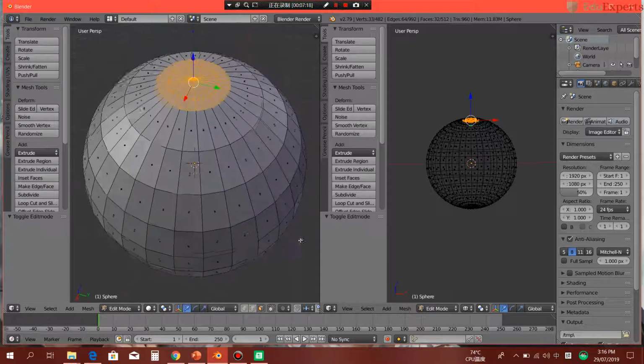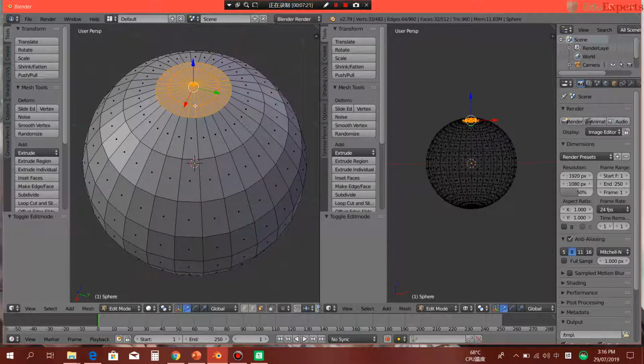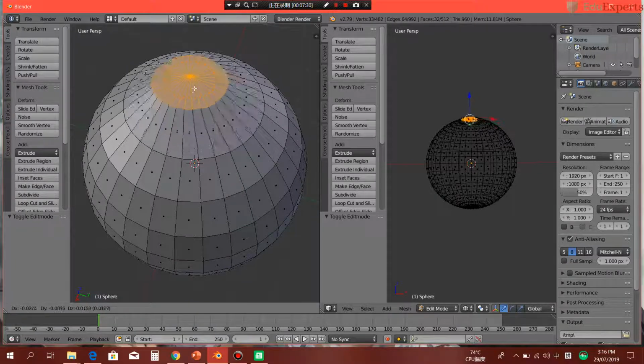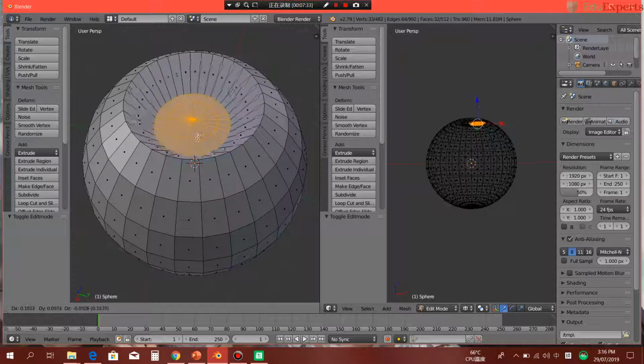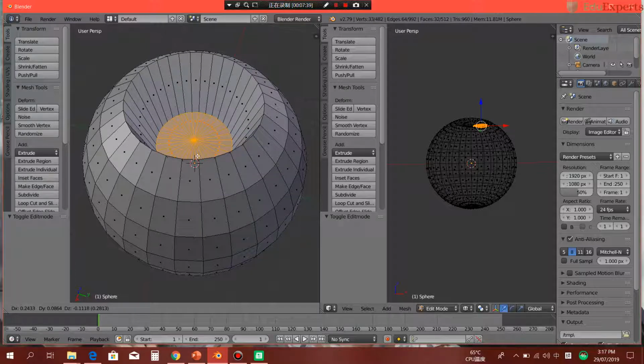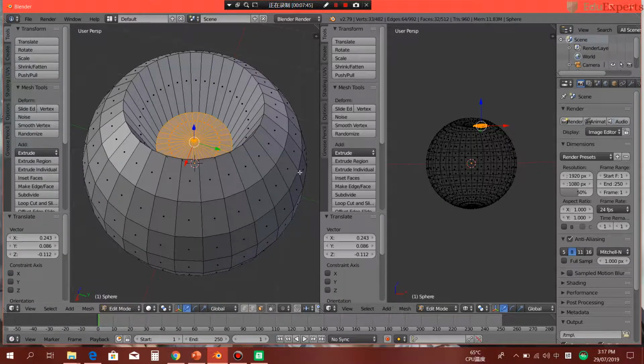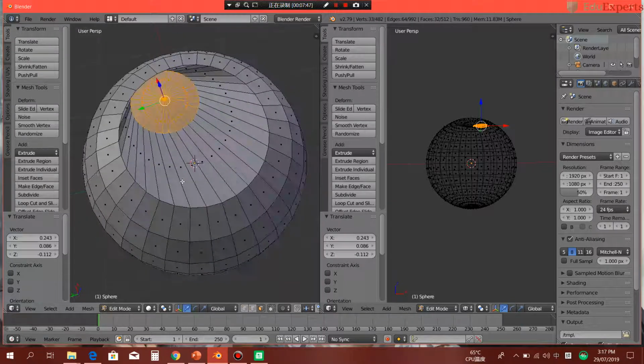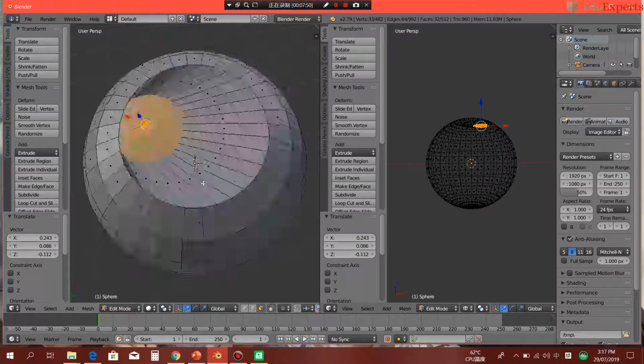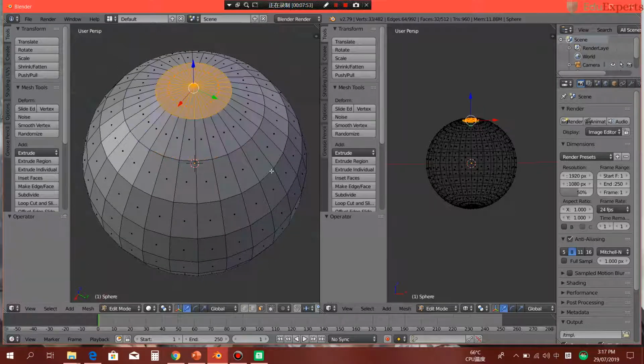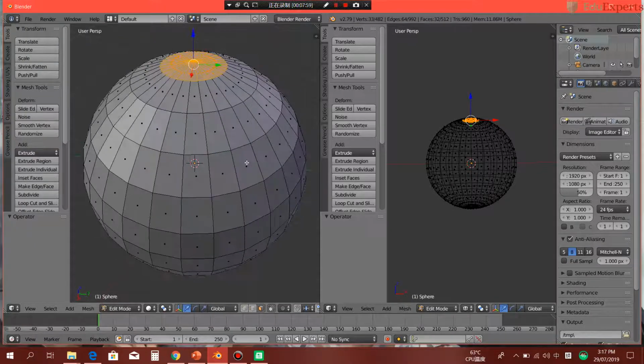The reason I'm doing it in the set view is quite easy. If I want to drag this part down a little bit, I can press the G key. G is short for drag. If I press that and drag it up and down, it can't be accurate. I can't make sure the going down part is the center area of this ball. Even if I did this, and you have a look, turn around, you can see, oh, it looks ugly. Totally goes to the wrong position. So I use Ctrl plus C to cancel that movement.